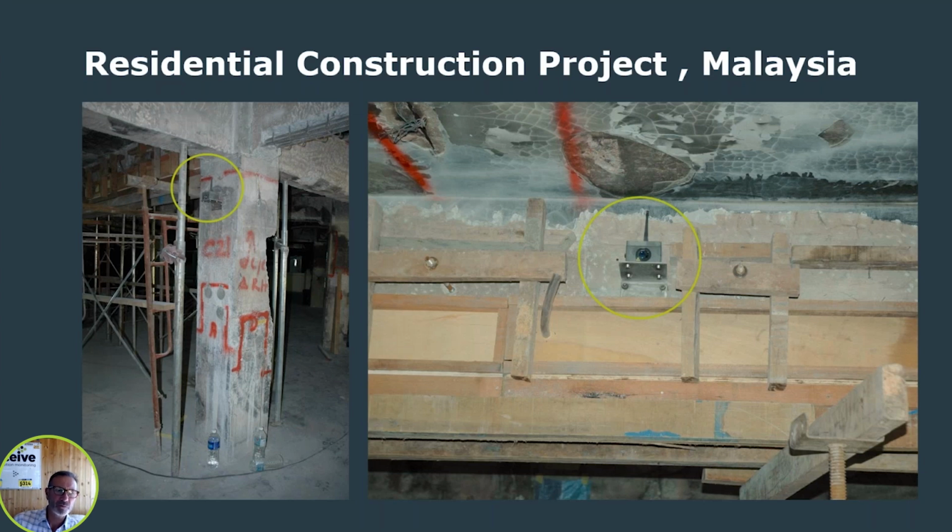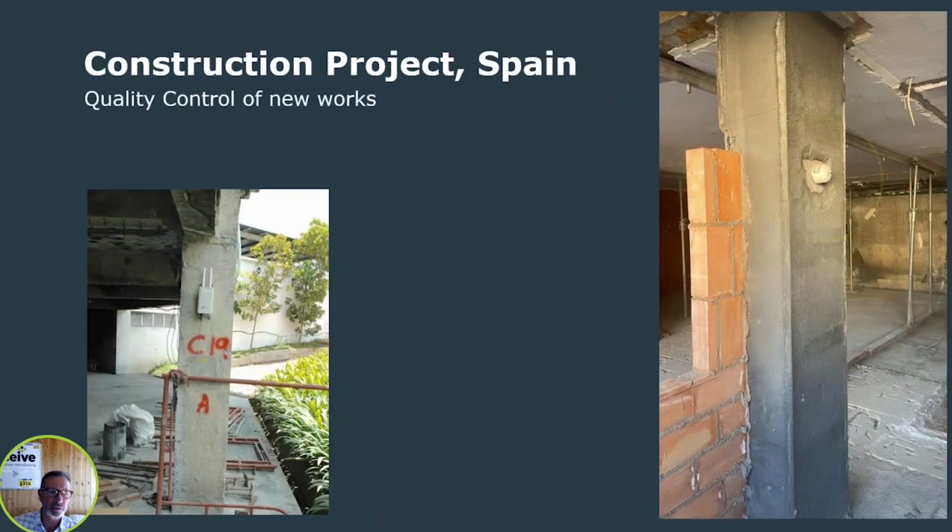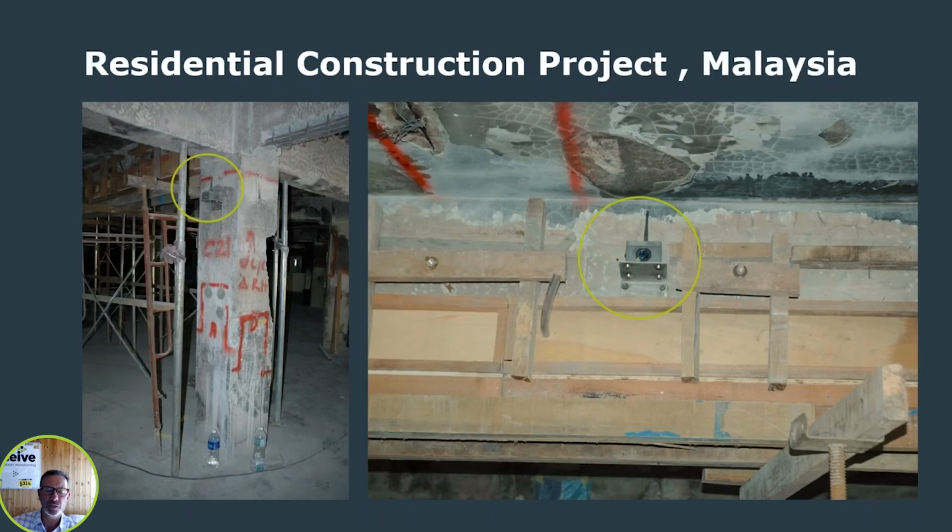So you can see here some concrete columns where there have been issues with the concrete pour. There's a big notch out of this concrete column here, and a tilt node, an optical displacement sensor, has been fixed to the column here, looking across at a solid object within the line of sight to look at the relative displacement of these objects. And these were fitted to a number of beams and columns around the site, along with tilt nodes and a gateway to provide the cellular coverage.